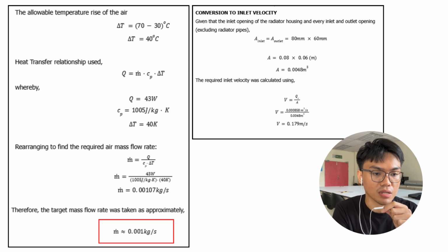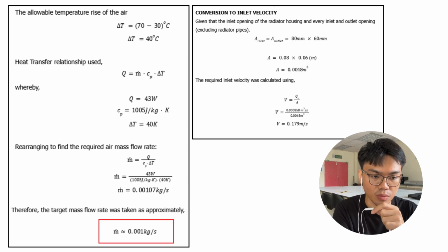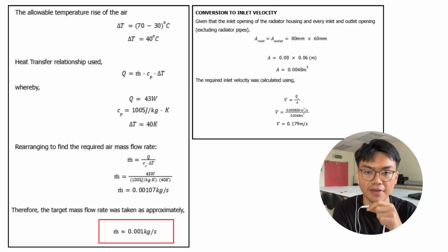From the flow trajectories, we can see that the air enters through the circular inlet pipe, rotates through the impeller region, and is then guided by the volute housing towards the rectangular outlet. The pressure difference is very small, which is expected because the airflow requirement is low and the fan is only used to provide gentle forced convection. Therefore, 120 rotations per minute was selected as a suitable fan speed.